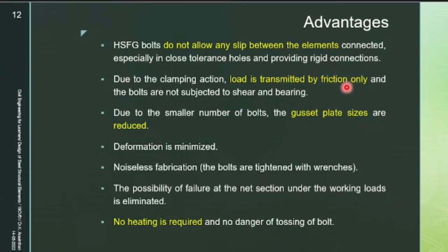This is another advantage. And the bolts are not subjected to shear and bending. Eventually, if you are using that, the gusset plate size will be reduced. Due to the smaller number of bolts, you can reduce the dia of bolt, and you can reduce the gusset plate size.